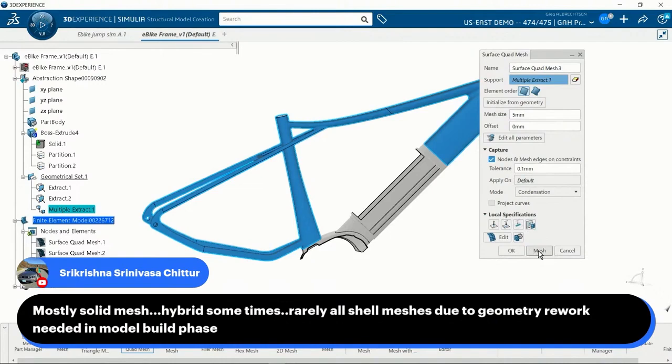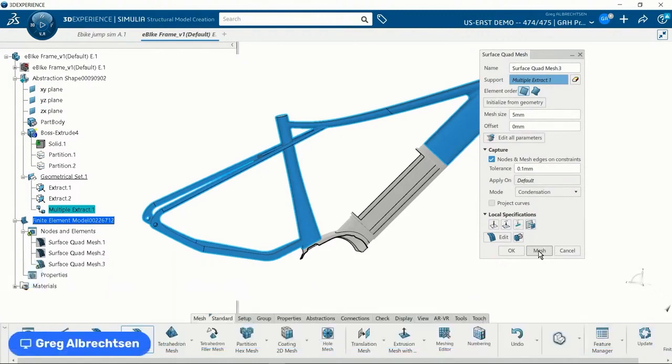Yeah, it's all about the shape of the geometry for me. Our TET meshing and our solving capabilities are incredible for TETs or hex or whatever you want to use there. Shells can solve much quicker because you don't need as many of them, perhaps. So it really depends on the level of detail, resolution, and accuracy in the solution you're looking for. But for this frame, I would do it exactly like I'm doing it here. I would shell mesh this.